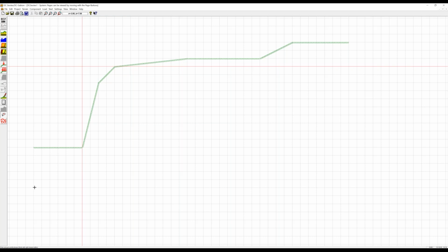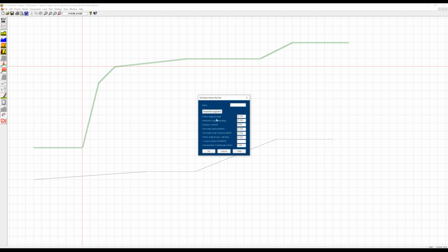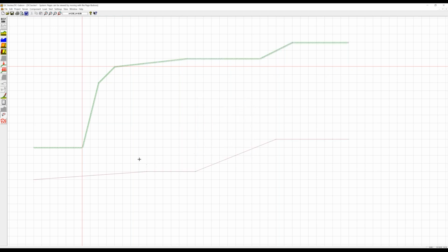As a difference to DC pit, for example, we don't have the classical calculation of earth pressure, but we have earth pressure calculation according to Kuhlmann, and this means we can have here an arbitrary shape of the soil layers which can be defined. Now here this could be some silt, for example. We can have a distribution of water level.